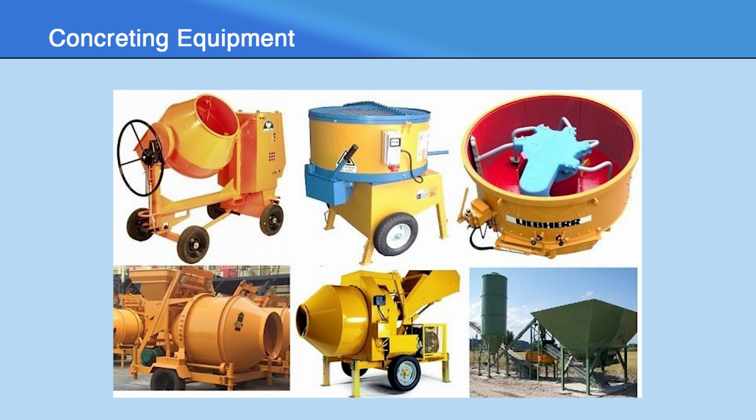The tilting drum mixer. The drum rotates around a trunnion axis and can be easily tilted for emptying the mix. This design allows the drum to be rotated and tilted both when it is full and empty. Closed drum mixers. In these mixers, the drum rotates continuously in one direction. The mix is emptied through a hopper that tilts to receive the discharge.